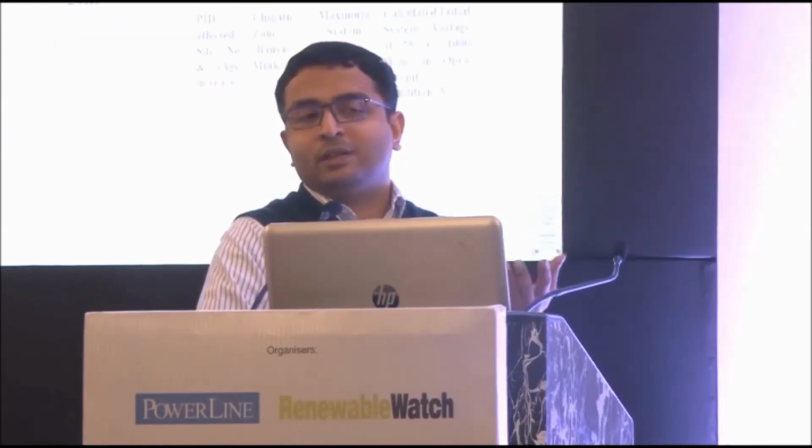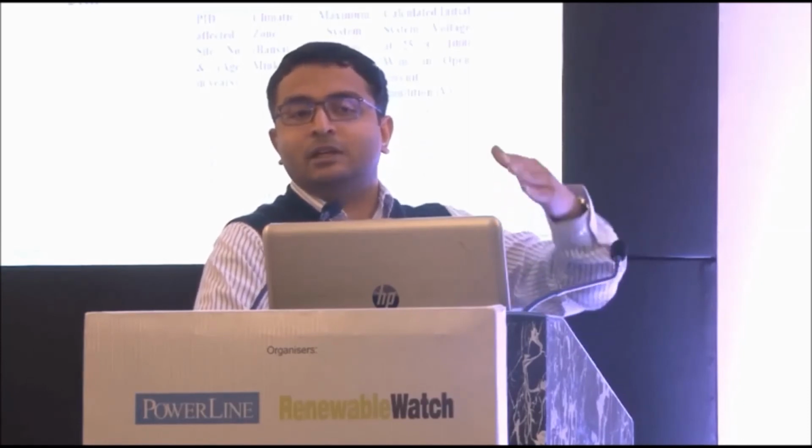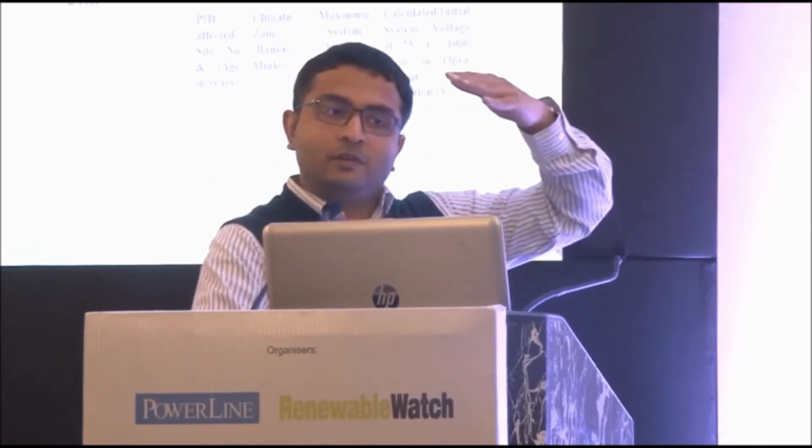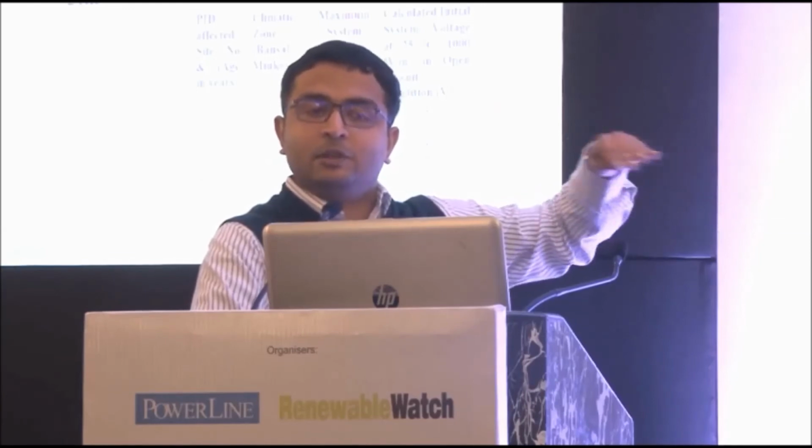As most of you already know, the way to detect PID is through electroluminescence imaging and then finding a correlation of this degradation rate with respect to the position of the module in the string. So we were able to see that in some strings of the same plant, the PID was not present, which was quite surprising to me because if it's the same module, then it should behave in the same way. But apparently that's not the case.